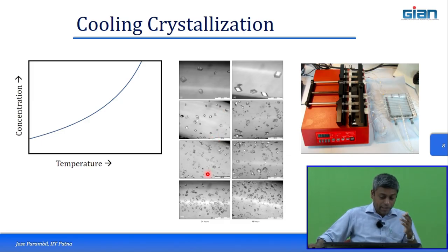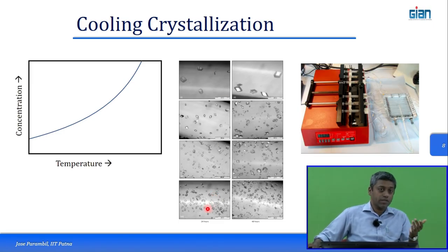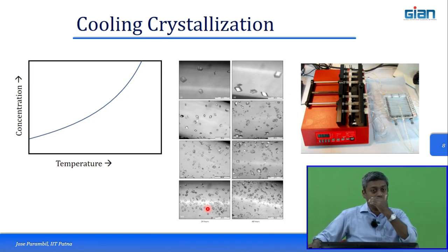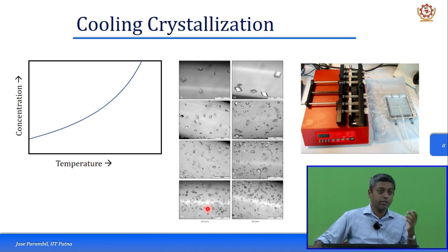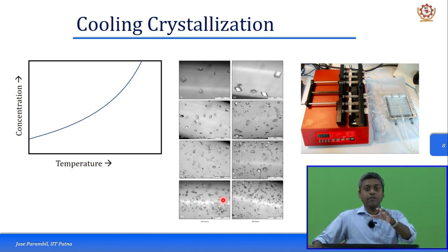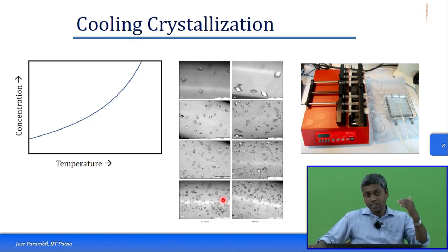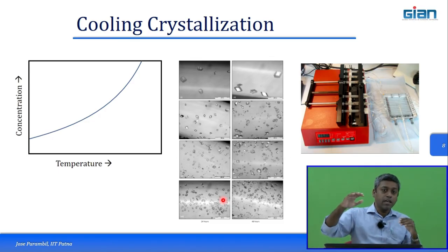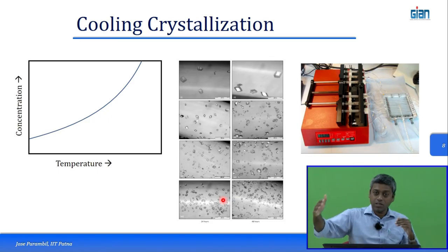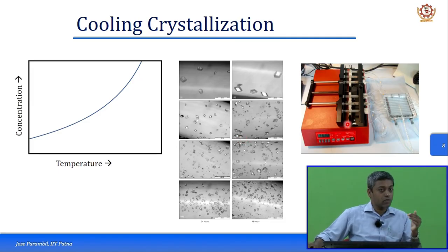In this particular case, as you increase the shear, you are getting more and more crystals, which means that the nucleation, or the birth of new crystals, is being affected by the shear. There is an optimal shear up to which the nucleation increases. Beyond that particular shear, it starts to decrease, and if you increase the shear further, it might even degrade the system.